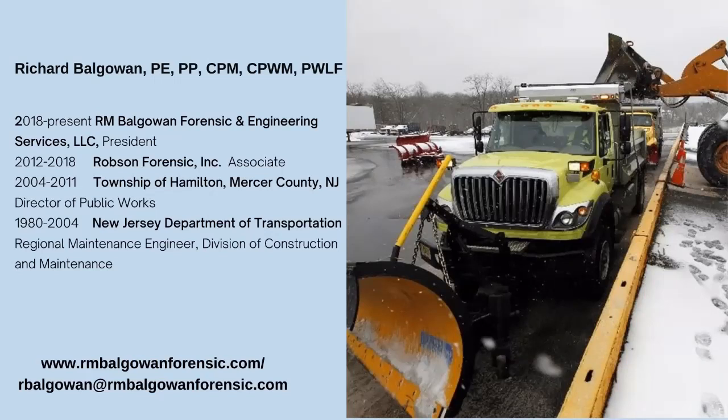And if one of your roads has a system like that on there, those sensors actually measure conductivity and inductance. So it will tell you the salinity of the salt solution that would be on the roadway. And then it would advise you when you should go back out there and reapply chemicals because the solution is becoming too diluted, and when the pavement temperature reaches a certain point, it's going to refreeze. So there are systems out there that you can use. Like I said, DOT has like 30 of them.